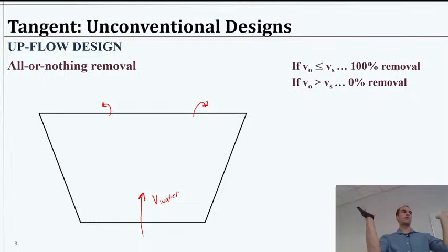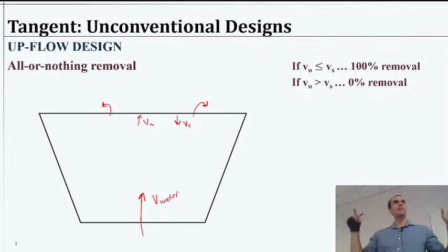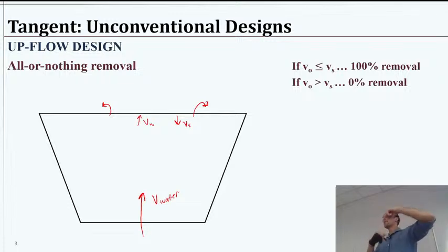Because this is shaped in this sort of trapezoidal manner, the water reaching the surface is going a little slower than it was when it entered towards the bottom. So we have kind of a smaller water vector. Now, we need a condition where the Vs has to be greater than that VW right as it's about to cross in order to have sedimentation. And theoretically, if it is greater, it's probably going to stay there just beneath, and we'll find some equilibrium, but then it'll probably meet other particles and stick to them and then get bigger and settle faster.